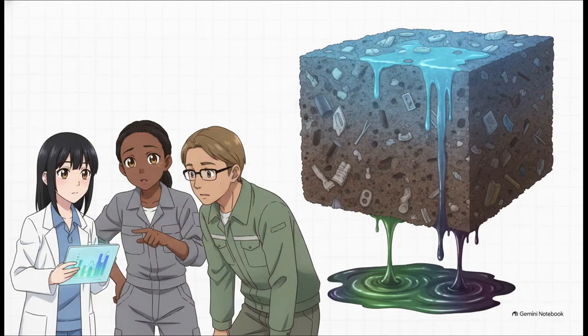Inside the landfill itself, engineers track something called field capacity. Think of it like a sponge. It's the maximum amount of moisture the waste can hold onto before gravity finally wins. Once the waste passes its field capacity, say after a massive rainstorm, gravity pulls that excess water straight down through the rotting garbage, creating highly toxic landfill leachate. And just like density, field capacity changes depending on how heavily compacted the waste is.